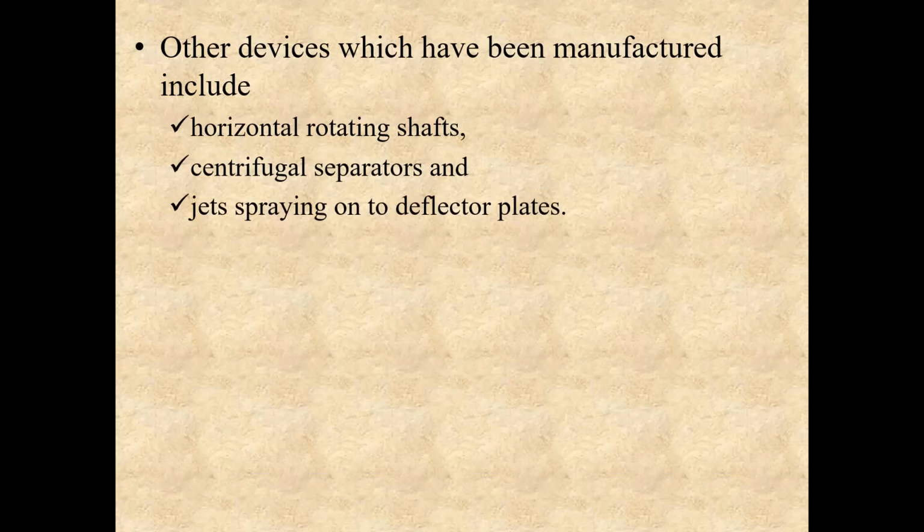Unfortunately, these mechanical foam breakers sometimes have to be used in conjunction with antifoams. For example, vinegar fermentation. You can't use a chemical antifoam in vinegar fermentation, and vinegar fermentation is often foamy. Why can't you use a chemical antifoam? Because it's not feasible, as antifoams may decrease the aeration efficiency, and vinegar fermentation is a highly aerobic process.